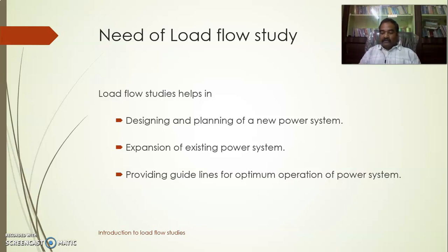I am going to set up a new transmission line and new system. For making this decision, whether to move on to a new system or expand this particular system, we need to understand the current state of the system. And that is done through load flow studies. It gives us the guidelines for optimum operation of the power system.